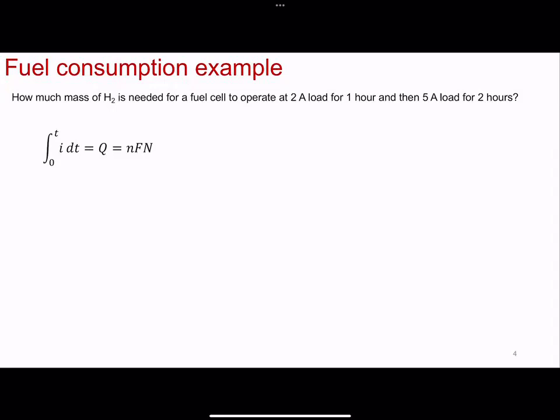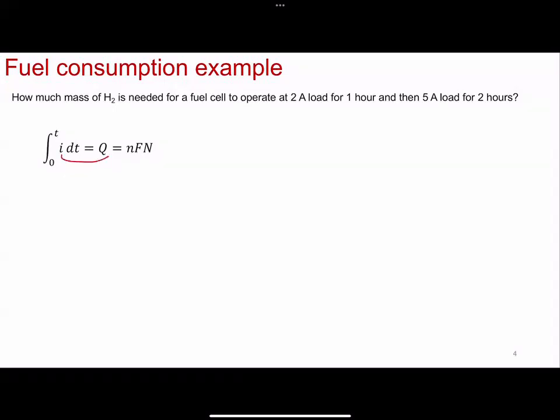Okay, so you use the same relationship, but now you've inverted it because now you integrate current over time. That's charge. Surprise, that looks exactly like a battery. That's exactly what you do. Constant current over time integrated is the charge that you get out of your battery. So two sides of the same coin, same equation.